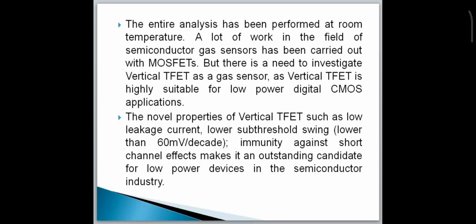A lot of work in the field of semiconductor gas sensors has been carried out with MOSFETs, but there is now a need to investigate the vertical TFET as a gas sensor. I am doing that, as the vertical TFET is highly suitable for low power digital CMOS applications. The novel properties of the vertical TFET, such as low leakage current, subthreshold swing lower than 60 mV per decade, and immunity against short channel effects, make it an outstanding candidate for low power devices in the semiconductor industry.